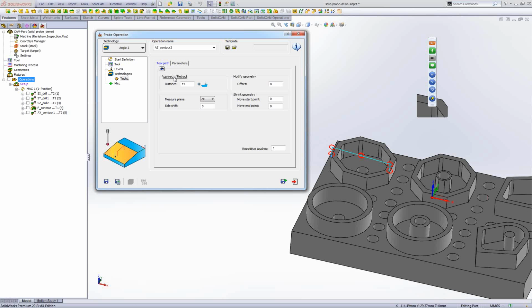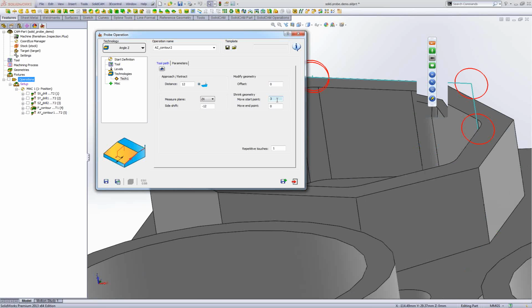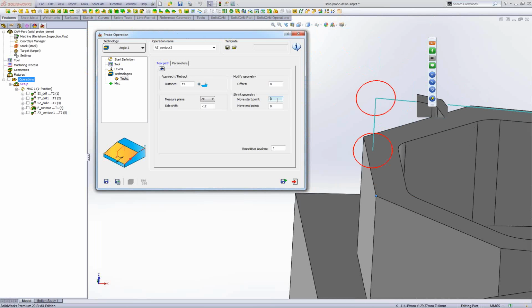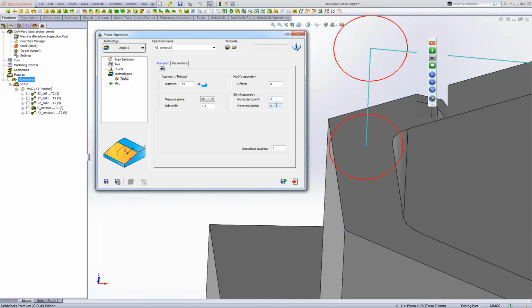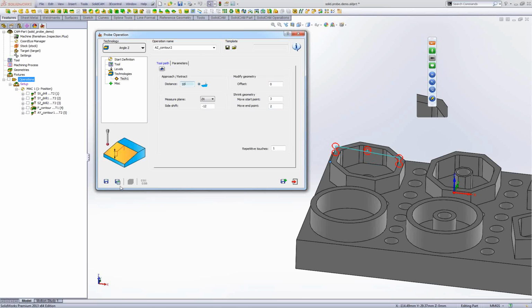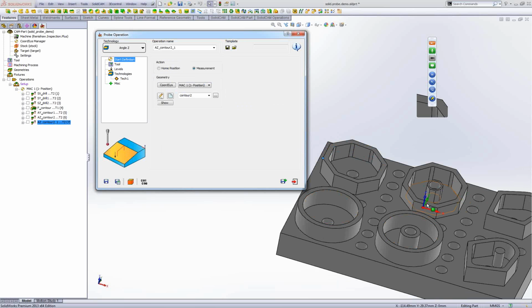Preview. Now the toolpath can be shifted, and of course start and end point, move it to a better position. Clearance, save and calculate. Save and copy, and now let's define a geometry on YZ plane.